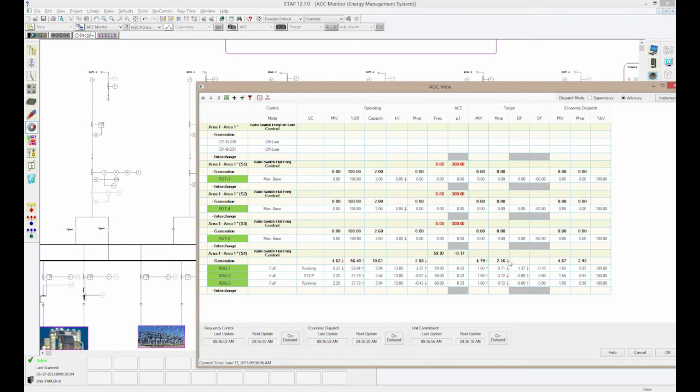So whether I should be operating in droop mode with my conventional sources, or should I switch them to isochronous mode and actually start regulating the frequency. In addition to that, there's many other minor capabilities inside the program. You're actually able to export this information out into Excel. So if you're actually trying to gain confidence in the system, you can actually run various tests with the generation optimization routines, generate the output and export them to Excel for further analysis. So we do have that capability.